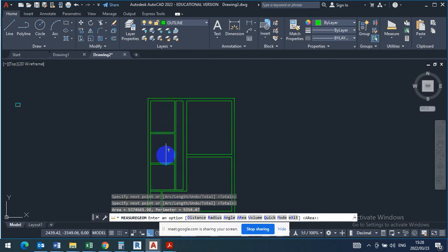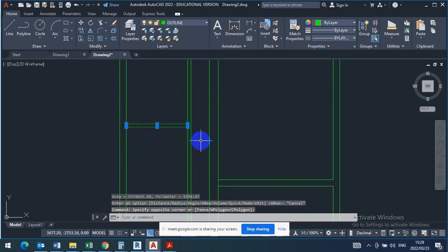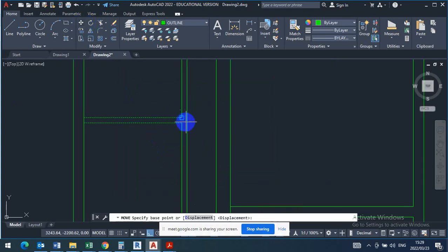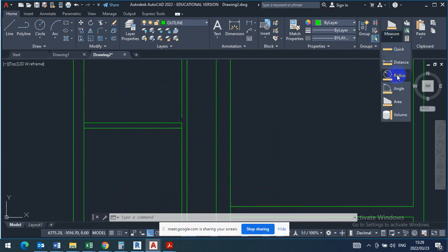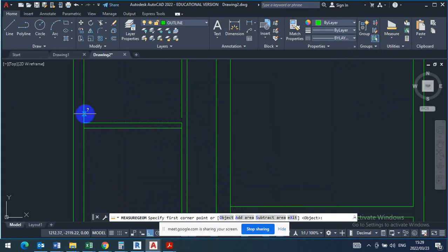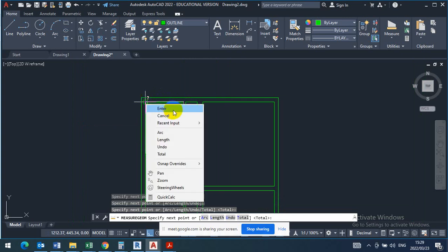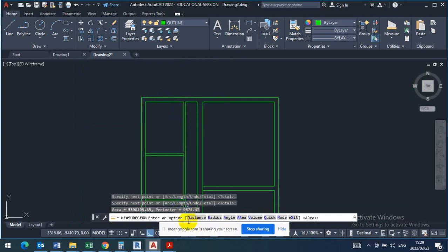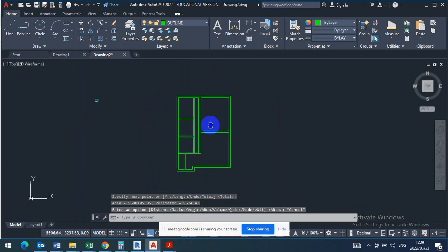You can move the walls down, you can drag these ones, move them a little bit. You can move them down maybe to here and try to measure the area again. It's room by room, just make sure that all your rooms are near the same area given by the examiner. Again, you start corner to corner, as long as you're around 11, and there right click, enter. All right, at least this one is 9.5, so it's still small. Continue working with that until you finish.